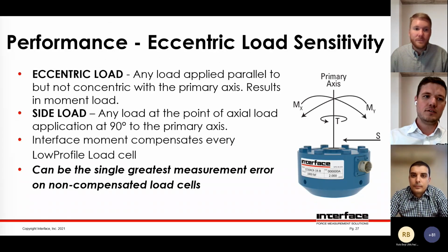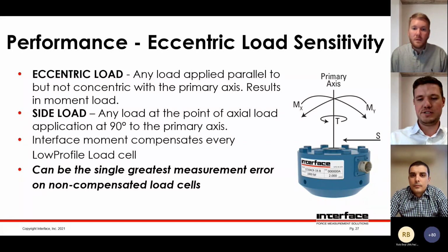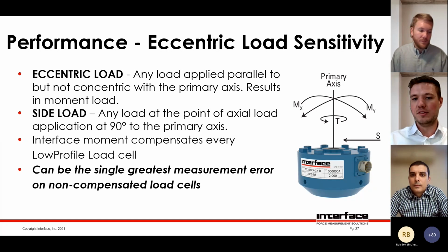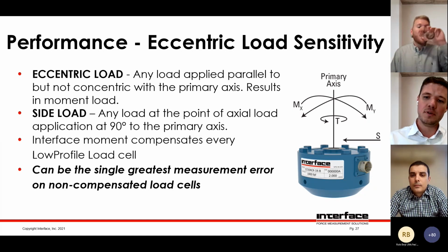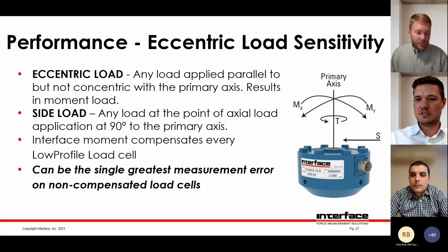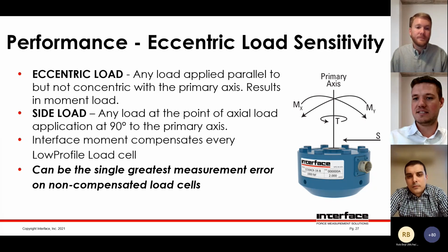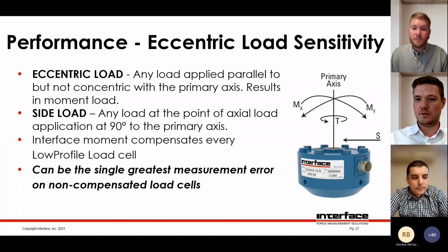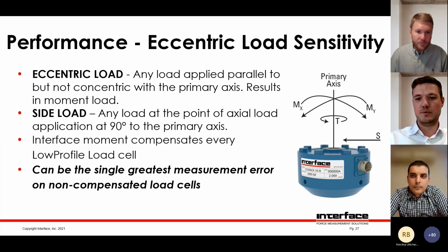Thank you. So we mentioned eccentric and side loads before. The definition is any load that's not applied in the primary axis, so through the threads in the center of the load cell. The design of the interface load profile is specifically set up to be very insensitive to off-axis loads. So the load profiles deal very well with small moments or small side loads. And that is a really great feature of them, and not a lot of competitors can do that.